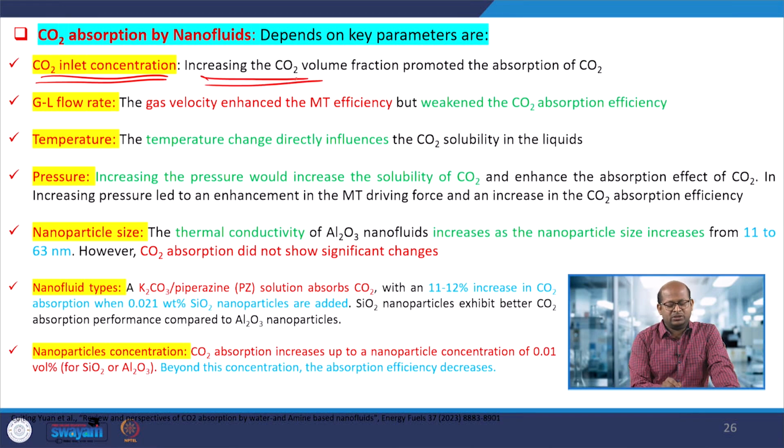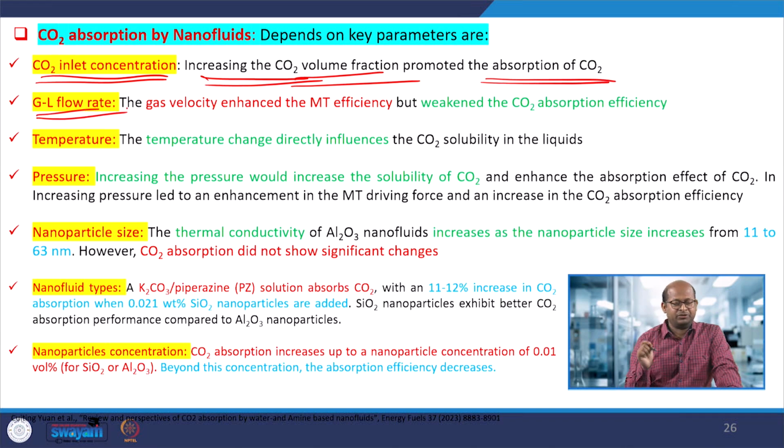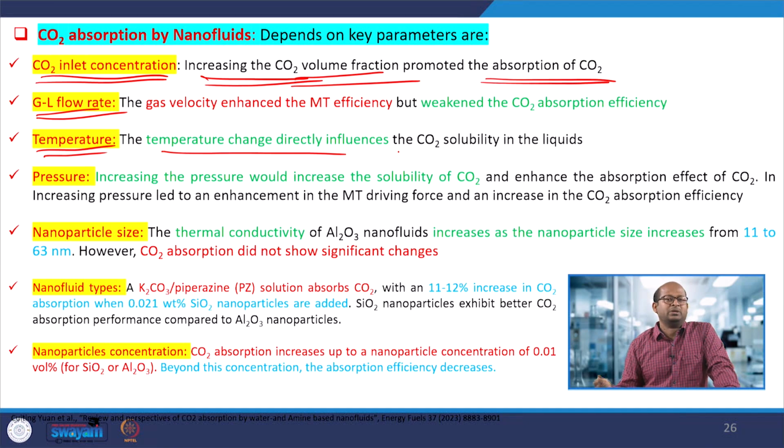If we increase the CO2 volume fraction in the flue gas, that would enhance CO2 absorption. Gas and liquid flow rates are also important, as they change the mass transfer of CO2 gas into the base fluids. Even temperature, as I said, normally we use low temperatures for adsorption, so 25 degrees centigrade is very suitable. If we increase the temperature, adsorption of CO2 in the nanofluids will decrease. Increasing pressure would increase the solubility of CO2.